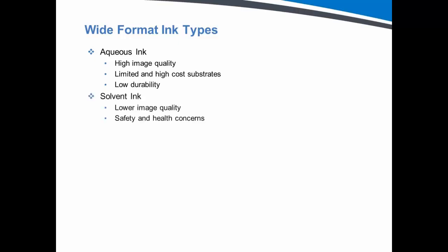Next is solvent ink, just about the absolute opposite of the aqueous ink. The image quality isn't that great, and there's some safety and health concerns because it's a hard solvent ink, so it requires some ventilation, and you don't want to be working around it too long.